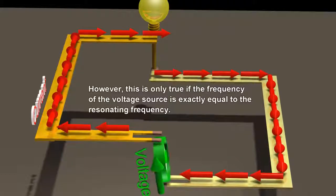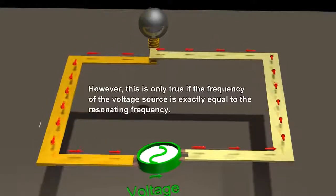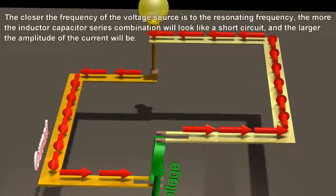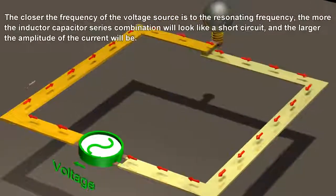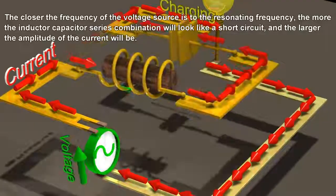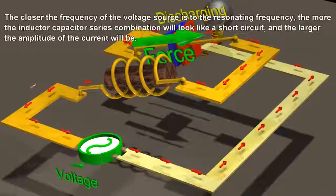However, this is only true if the frequency of the voltage source is exactly equal to the resonating frequency. The closer the frequency of the voltage source is to the resonating frequency, the more the inductor-capacitor series combination will look like a short circuit, and the larger the amplitude of the current will be.